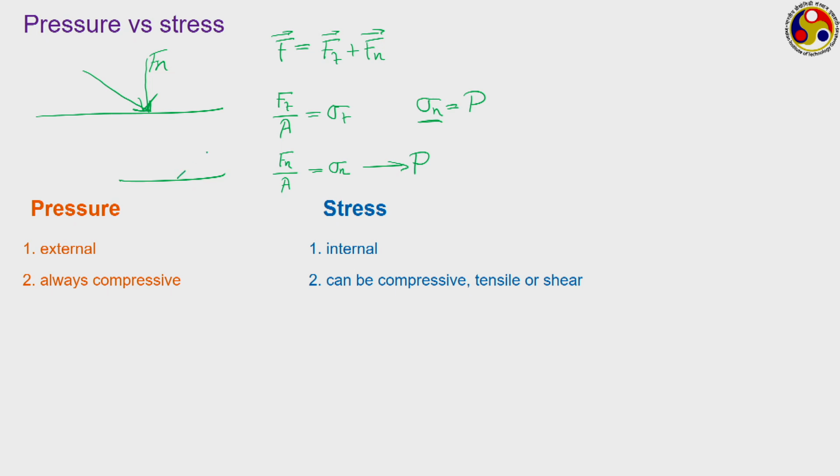However, if the force is say acting outwards and its normal counterpart is this F n, then this one will not correspond to pressure, rather its opposite. Like if we can draw something like this F n bar, let us say, these are all vectors, I am not putting the arrow. So, pressure will correspond to this F n bar. It is always compressive in nature, always pointing into the surface. That is not related to stress.